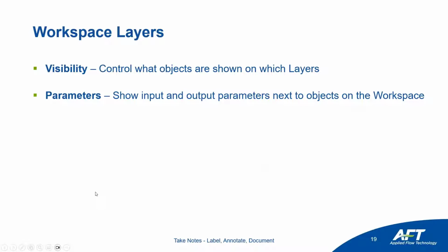The next thing we'll show is, along with controlling what we show for each of the objects, we also can show parameters for each of them. So if we have visual report users, this is how we can control, do we show our pipe lengths or our nominal sizes? And then as we get into output, what are our velocities or what are our pressures throughout our piping system?